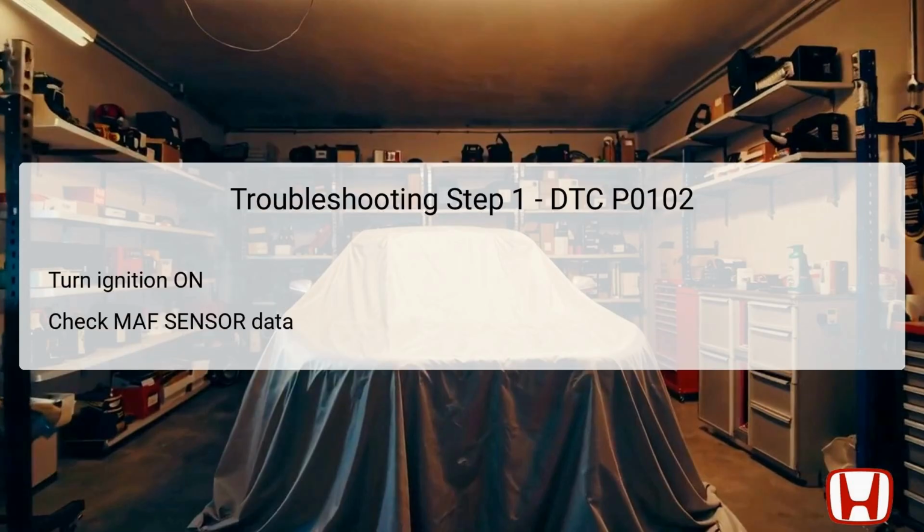The first step in troubleshooting DTC P0102 starts with problem verification. Begin by turning the ignition switch to the on position, 2, and allowing it to sit for about 2 seconds. This step is crucial as it enables the vehicle systems to initialize correctly. Next, access the engine control module, ECM, data using the Honda Diagnostic System, HDS. Focus specifically on the MAF sensor reading in the data list.